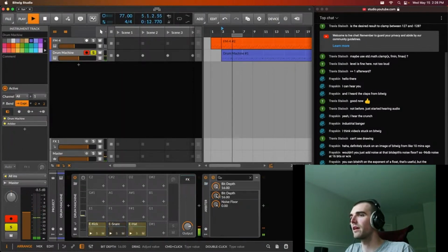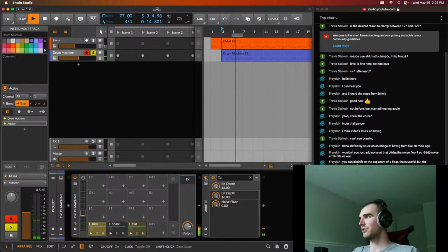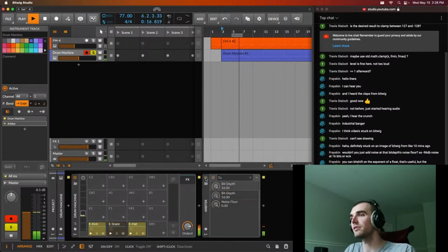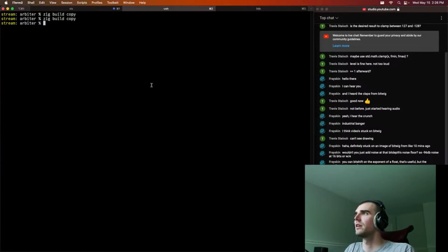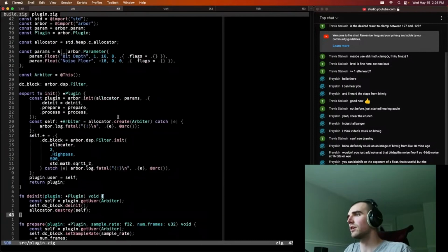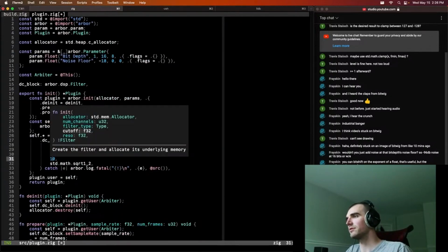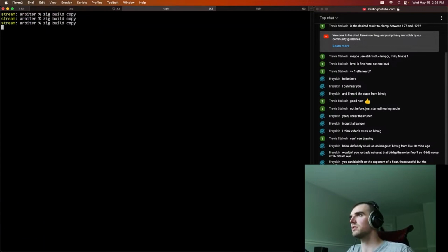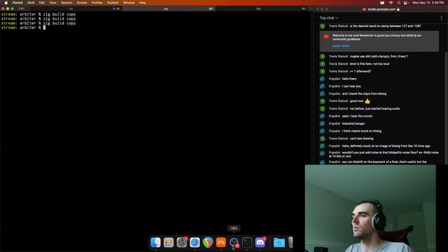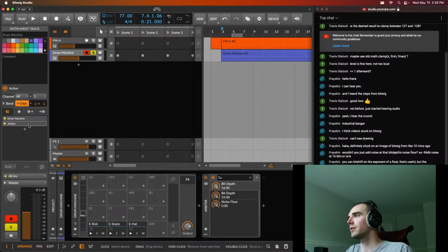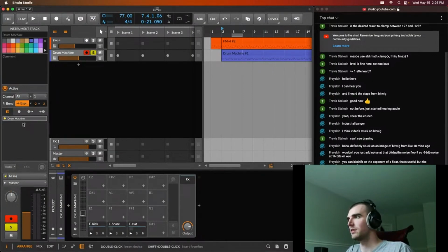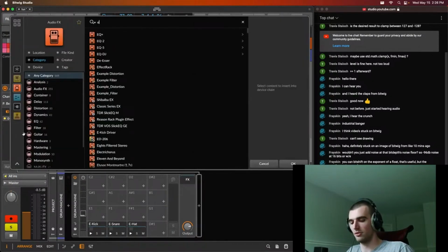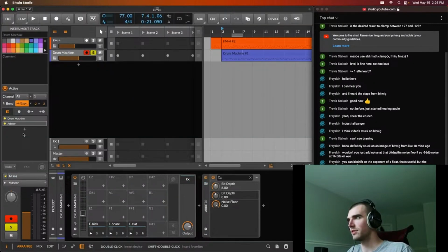Okay. And that is what we wanted, which is a high pass at about 500 hertz. So let's set that back to the value that we want of just 10 hertz, which should just block any DC from coming through when we start really messing around with bit shifting operations and stuff.